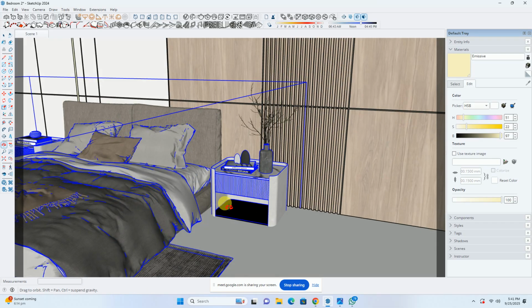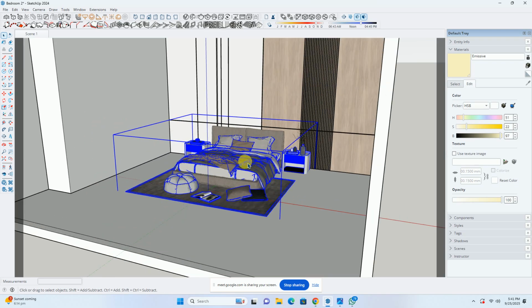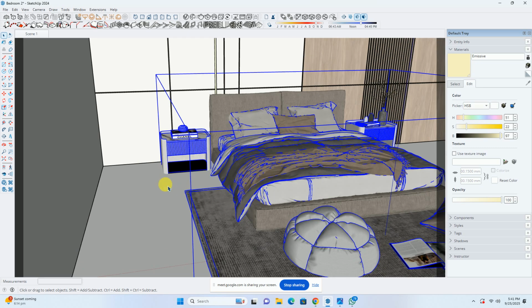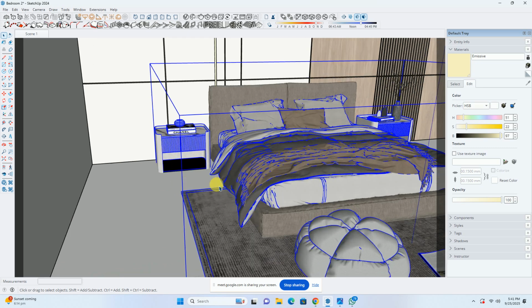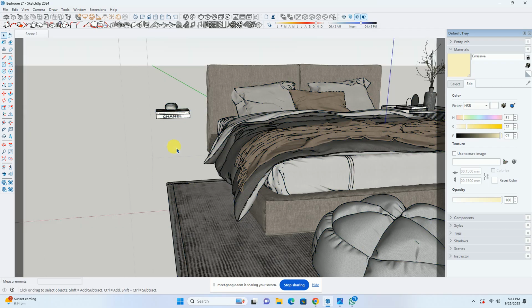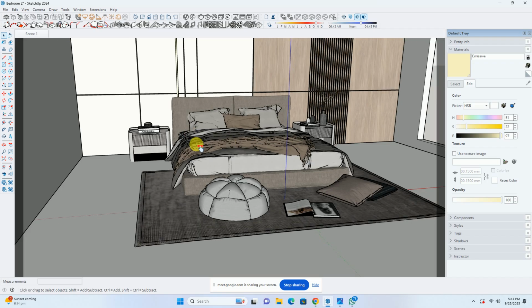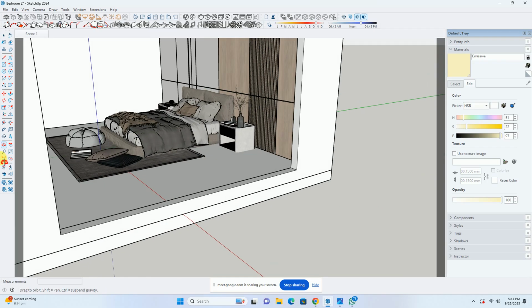Because we have moved the complete element downward, the side table will get below this element. So because we are creating our own side table now, we can just simply select and delete this element. Or you can hide these elements as per your own needs, whatever you want.